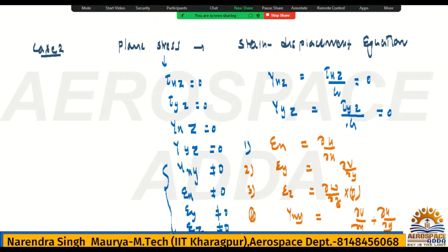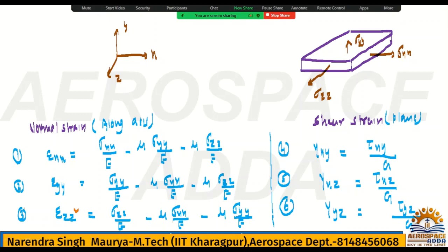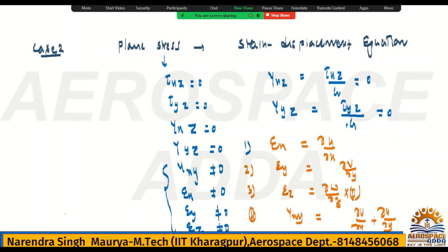displacement in z direction. So in terms of strain displacement, you will have only 3, because epsilon z is dou w by dou z, which means displacement in z direction. But it doesn't mean epsilon z becomes 0. You will get epsilon zz because of the lateral stresses sigma xx and sigma yy. So strain in z direction you will get, but the strain displacement relationship in z direction will not be feasible, because it's a plane stress condition, so the z axis is 0, hence there is no displacement in z direction. Hence you will have only 3 strain displacement relationships. Is this clear or not, dear? Tell me.